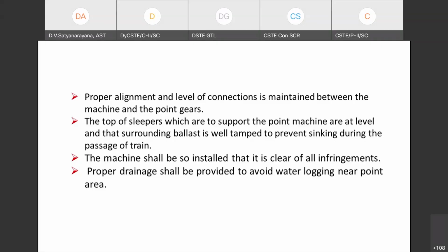Normally, we do some point machine wiring alterations if such cases arise, like instead of connecting to the normal side, we connect to the reverse side, something like that, especially in complex yards. Yes, sir. Is it okay? Sorry, sir, please repeat. Suppose an RH layout is inserted in place of an LH layout, where an LH layout is shown in the ESP, but due to some reason an RH layout is inserted. Okay, so we do some wiring adjustments. The point machine is wired in such a way that it suits the RH layout. It operates as an LH layout.